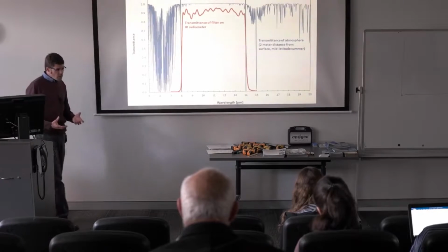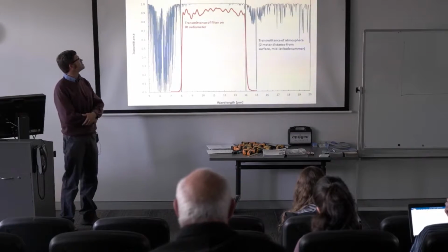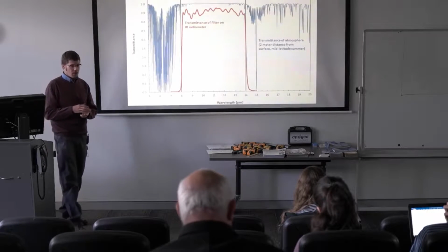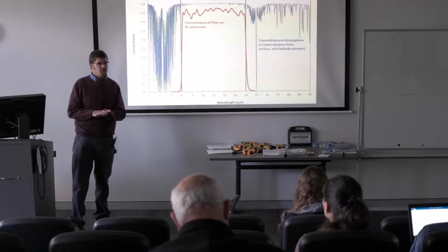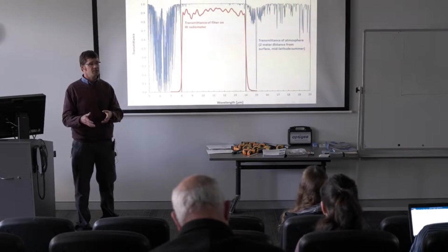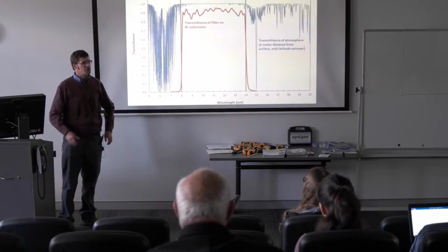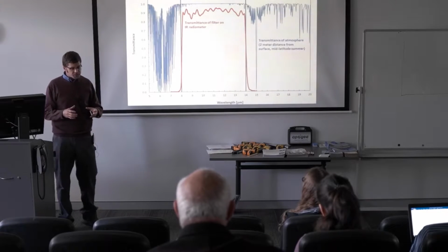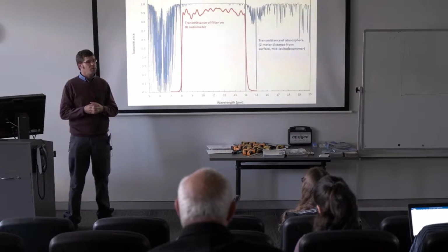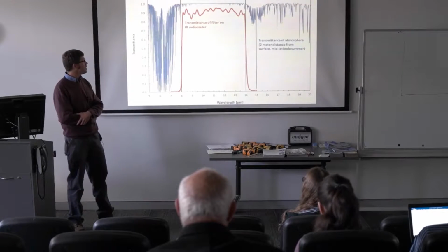All right, so another important component of infrared sensors that I didn't actually list on the previous slide is the filter that goes in front of the radiation detector. Radiation detectors tend to be black bodies, meaning they're good absorbers of all the wavelengths of radiation that are incident on them. Remember, we only want to measure the wavelengths that are related to the temperature of the surface. And so in order to build a radiometer that measures what we're interested in, we have to put a filter in front of it to give us just the wavelengths of radiation that we're interested in.